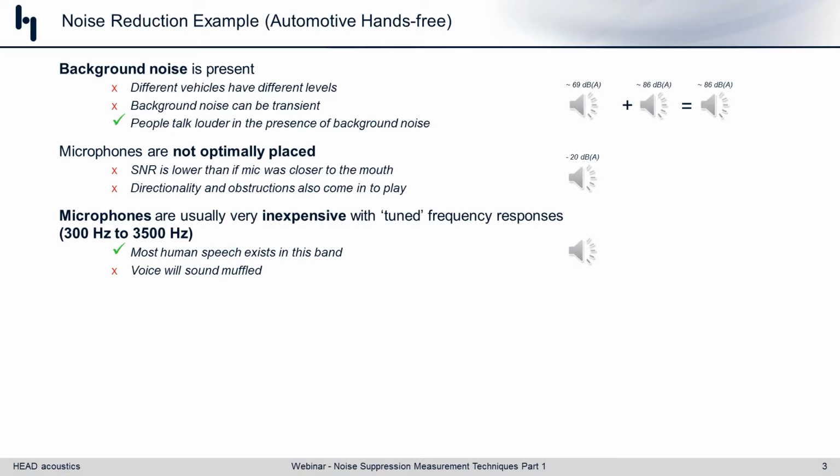And in some cases, in an analog fashion, have been tuned or designed to simply cut off at certain frequency ranges. It's not uncommon, especially for vehicle applications and mobile phone applications, to choose transducers that simply don't have any sensitivity at the very low frequencies.